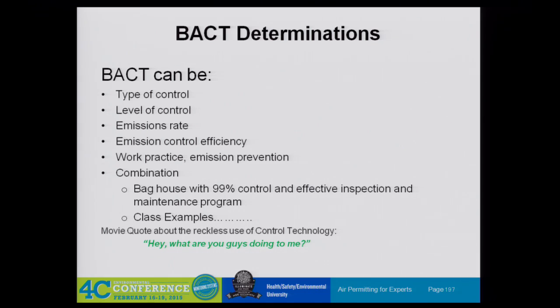Oh, there's all kinds of things, like design redundancy for sulfur reduction systems or sulfur plants, that don't really have anything to do with control, except in situations where you need to have shed steps or something for acid gas going to your sulfur conversion unit. So they'll build in a redundancy type step or some of that kind of stuff. It really doesn't fit the traditional philosophical BACT approach, but there's a lot of things like that. They make sense, and over the years they've just gone into this bigger bucket that we call BACT.